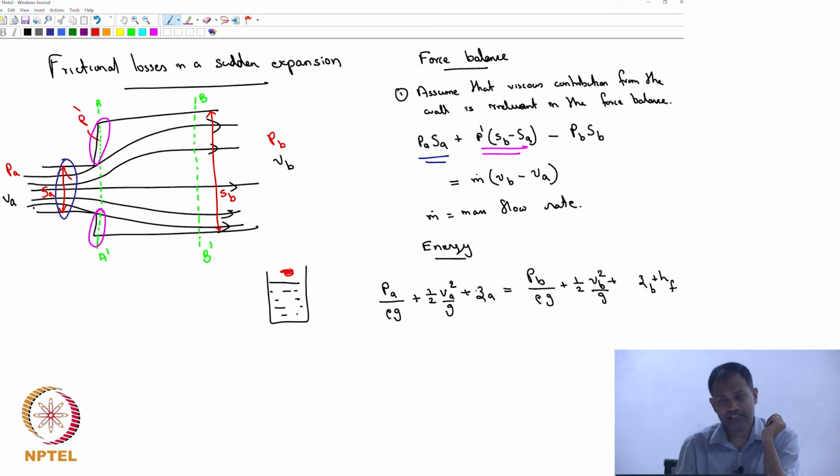Even if the pressure here is 0, you have a hydrostatic pressure that will arise, which will act on all sides of the wall, and that pressure will continue to increase. So the pressure need not be 0, it's completely independent of whether the fluid is moving or not moving. So the pressure could be some quantity. So the forces that are acting on a solid surface need not be just viscous, it could be pressure force also.